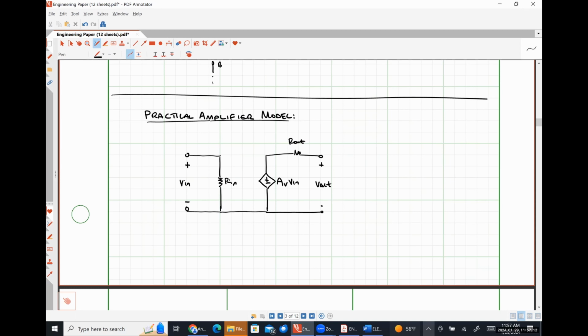And we said that our amplifier was effectively fully described by three quantities: our input resistance, R in, our output resistance, R out, and our voltage gain. If we knew those three quantities for our amplifier, it doesn't matter how internally complicated the amplifier was, we could use this circuit and effectively come up with the same result. We are going to take this approach to transistor amplifiers.